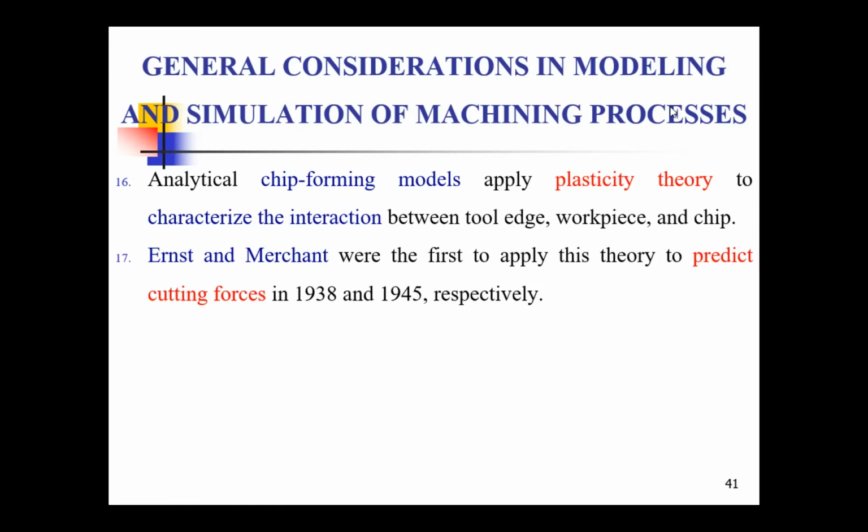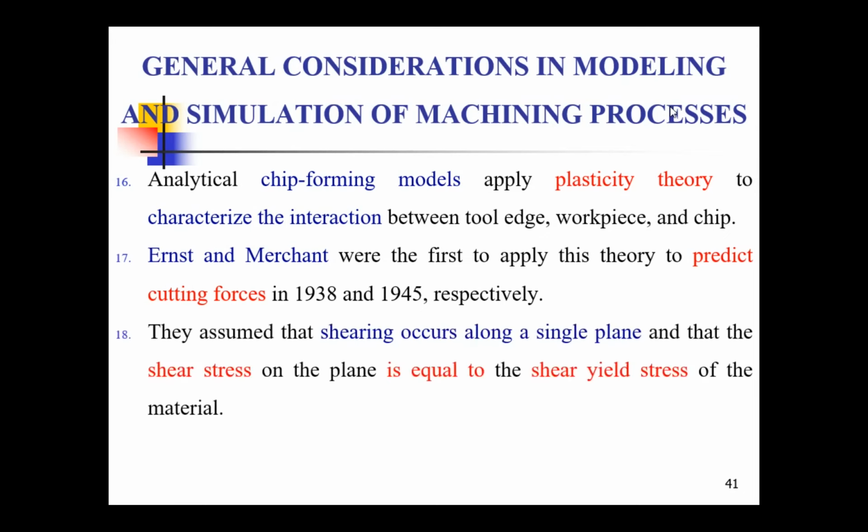Ernst and Merchant first applied this plasticity theory to predict the cutting forces, in the year 1938 itself. They used the shear plane model. Earlier we have seen that the theory of Ernst and Merchant uses the shear plane model. Shearing occurs along the shear plane and the shear stress on the plane is equal to the shear yield stress.